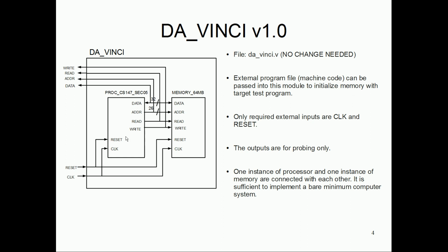The processor knows the next instruction fetch address, which is basically a memory read. It sets up the address for that instruction, sets the mode to read, and then simply reads whatever data comes from the memory, which it takes as an instruction.